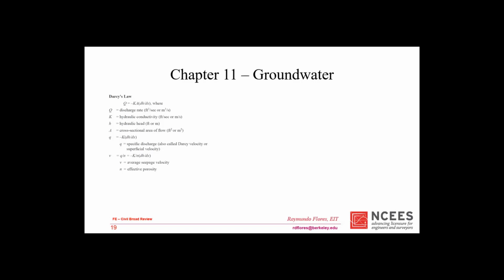So right now I want to focus on something called Darcy's law. From our point of view, Darcy's law is a differential equation. Well, it's not the differential equation, but Darcy's law comes from a differential equation. So if you have Q equals minus K times A times dH/dx, H is the total head at any given point, and here we're talking about a spatial dimension.